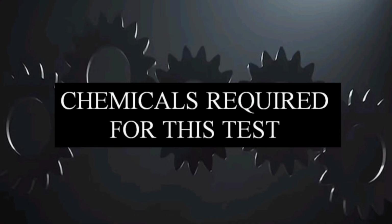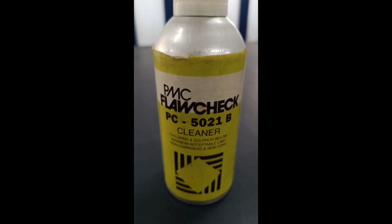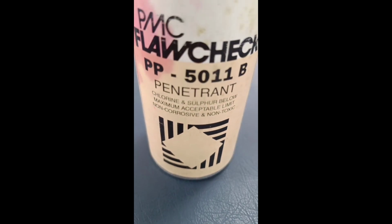In this test, we are required mainly three chemicals: cleaner, penetrant, developer. Cleaner. It is used to clean the surface of the stem and remove the excess left after the penetrant is sprayed.